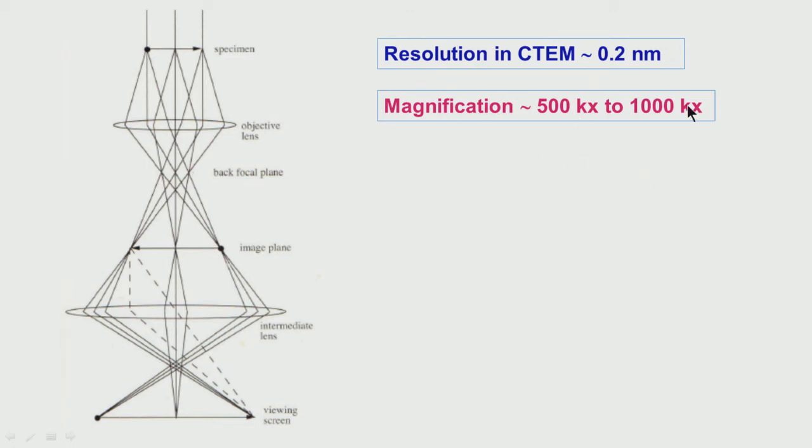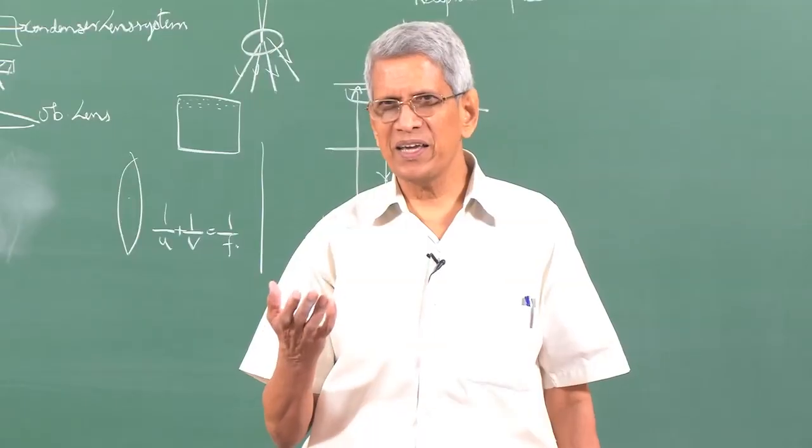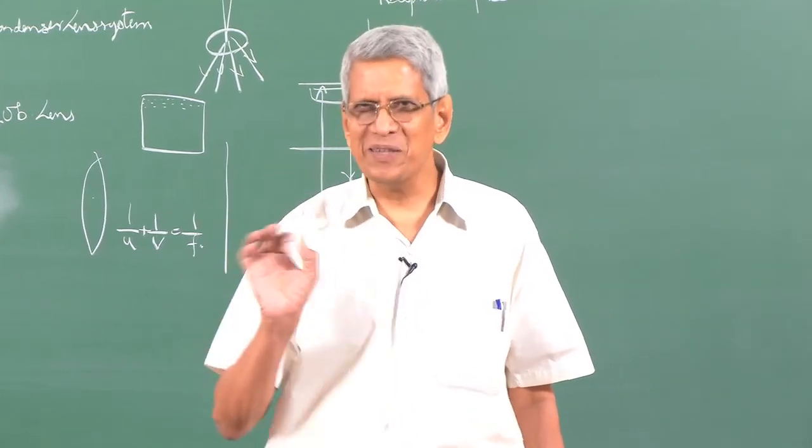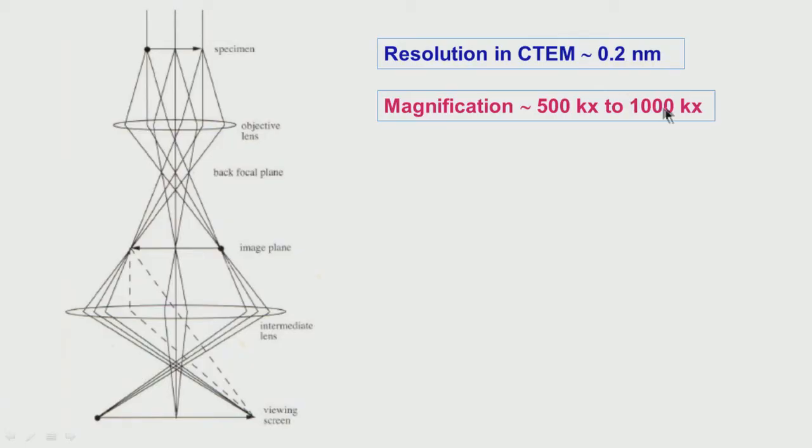The question comes, why do we require this magnification? If we wanted to resolve a feature of this resolution, when we talk about resolution, finally we want to see with our eye. That means 0.1 or 0.2 millimeter is the separation that the feature should have. So, this divided by the resolution gives you the minimum magnification to which the object should be magnified. If you magnify it further, we can see with our eye without any strain. Otherwise, at the minimum magnification, it will still be straining, but we can see them separate. That is what essentially is being done.